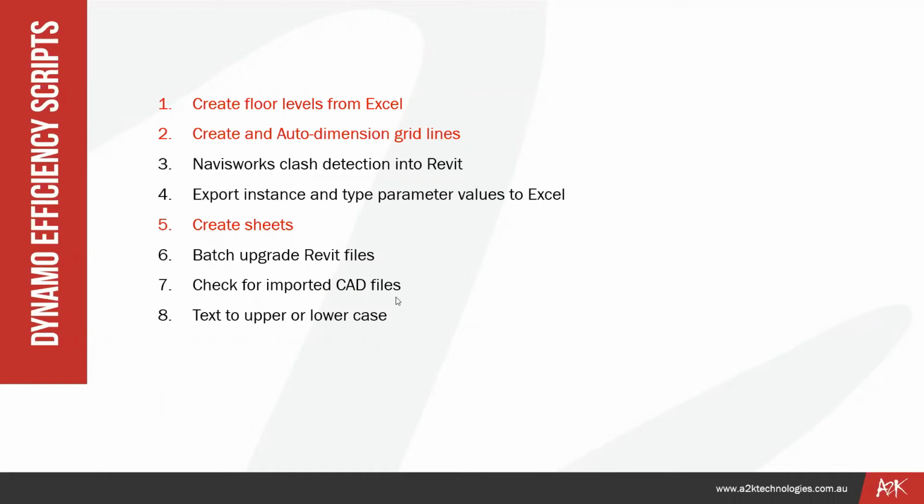Check for imported CAD files. So that's quite a valuable one as well. If you've all been using Revit for a good time, you do know that you should get a slap on the back of the wrist every time you are importing CAD. You should always link your CADs.